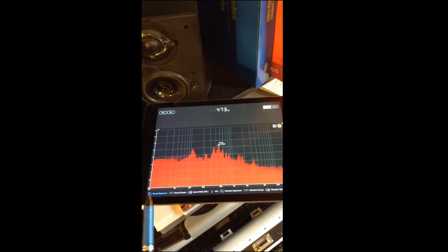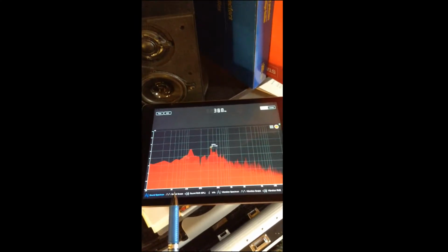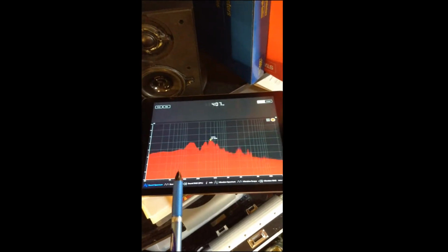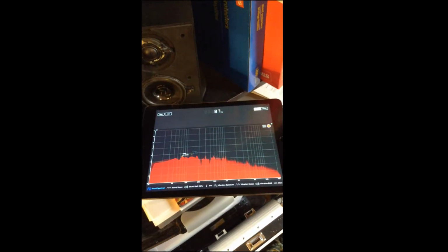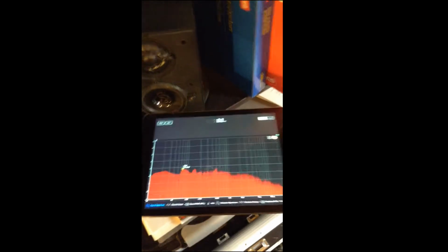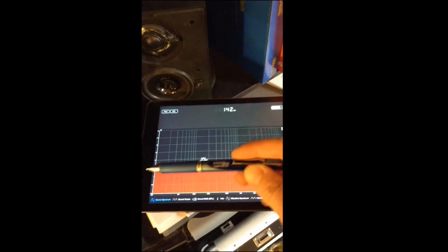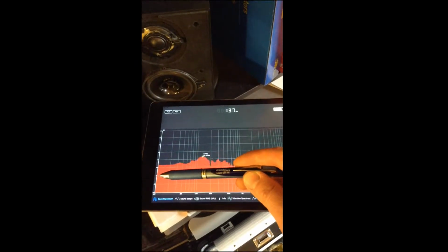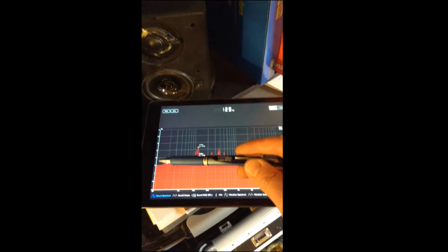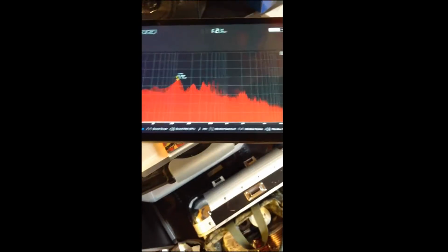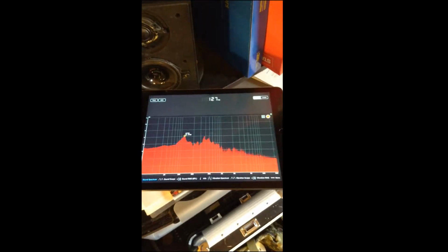You can't see this very well, but this is 20 Hertz, this is 50 Hertz, this is 100 Hertz, so our 60 Hertz range is going to be right about here. But this is a free app, so I definitely don't have enough money to buy my own Tektronix spectrum analyzer or something like that. So this is the best that I can work with. But if you look on the side, this is negative 40 dB, negative 20, 0, 20, 40. So each graticule represents a 20 dB difference, which is pretty significant. So this is limited, but it's the best we can do.